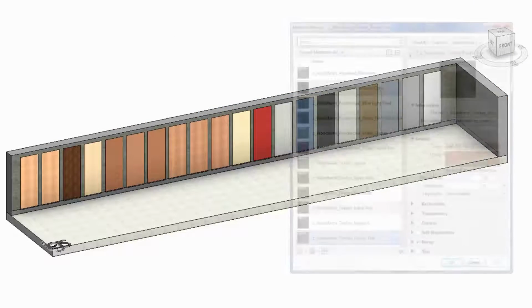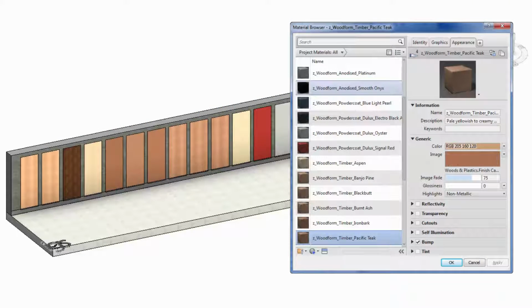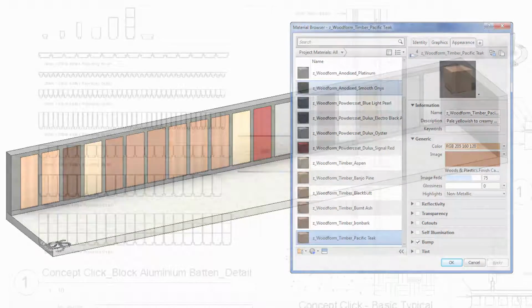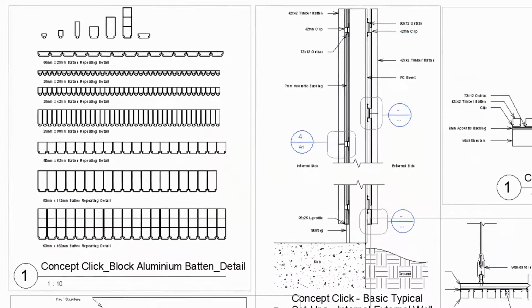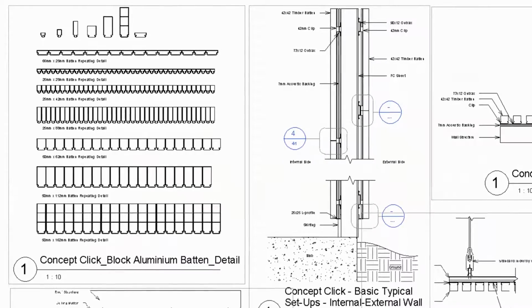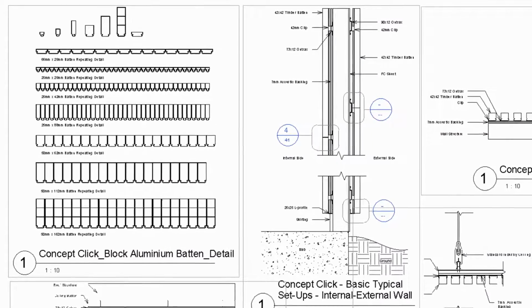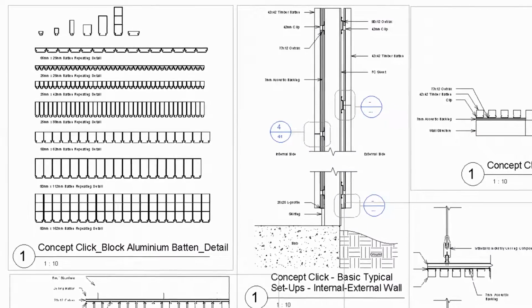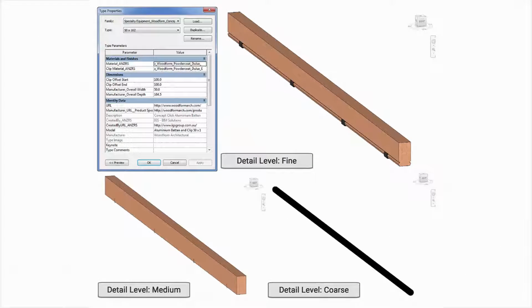This includes a basic materials library representing typical Woodform products, a selection of different 2D Revit families including profiles, a component library, a repeating detail library, and drafting views already pre-built. We've also included loadable families where you can create custom configurations in a 3D sense, which we'll explain later.